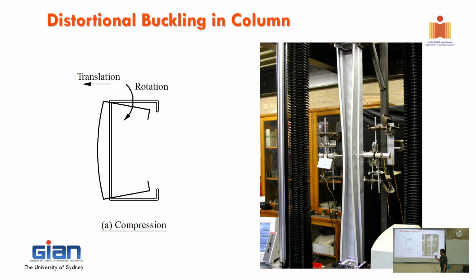Right, so I will explain later on. However, remember distortional buckling and local buckling are section capacity. It's nothing to do with length. As I explained to you, if you have double length, it's going to go in and out and in and out, but the column is still straight. Imagine you have a lateral restraint. And if you have triple length, it's going to go in and out and in and out over three half-wavelengths. So it's just multiples of the half-wavelength.